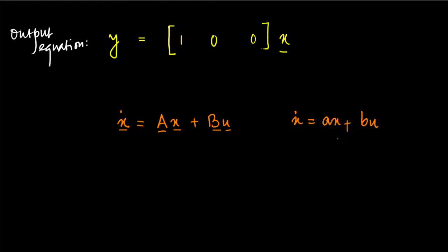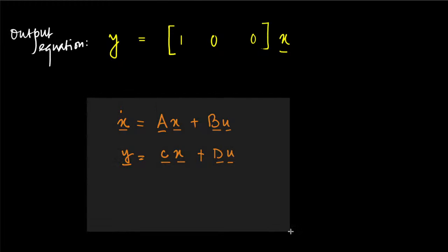So since this is sort of like a first order differential equation, we can apply certain standard techniques. Okay, and that's how this is so easy to use in a computer program. Much easier than using your transfer function techniques. Okay, and of course the output y is Cx, plus there is another term Du, which we are going to describe in a future class.